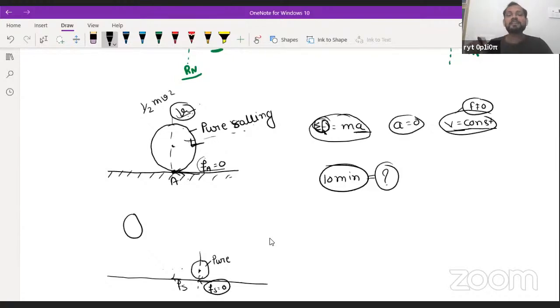So the kinetic energy of that body will go into the deformation, and after a period of time the complete kinetic energy is consumed in the deformation, or in hysteresis losses, or in permanent deformation. So this is the concept behind rolling friction. It does not depend upon surface irregularities, it depends on the non-elastic effects. Is it okay? I think this concept is clear to you.